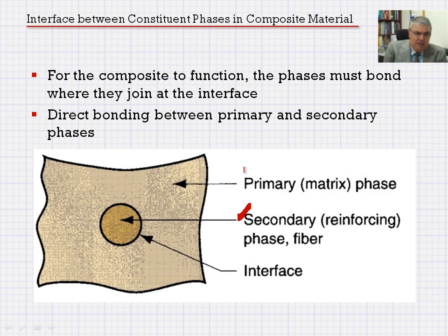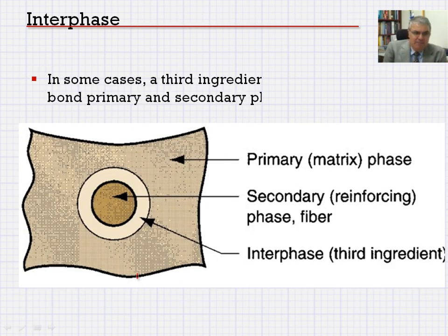This is actually where we apply the secondary reinforcing, and there is an interface between the reinforcing and the fiber itself. Most of the detachments that we see, where the fiber detaches itself from the primary matrix, happen at the location of the interface, because that seems to be where we have much stress concentration when we apply the load.